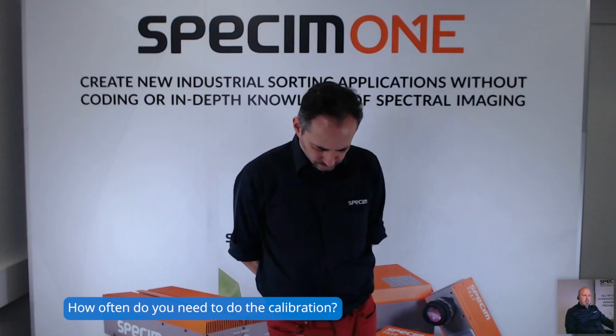Do you want to take the next one as well? How often do you need to do the calibration? I think it refers to the white and the dark reference. Do you want to handle that one as well? It depends on the sensitivity of your application. For example, for seal inspection, we know that they have to calibrate once per week. But when you have critical applications, for example, sorting PVC and PET, then sometimes it's necessary that you calibrate each day.